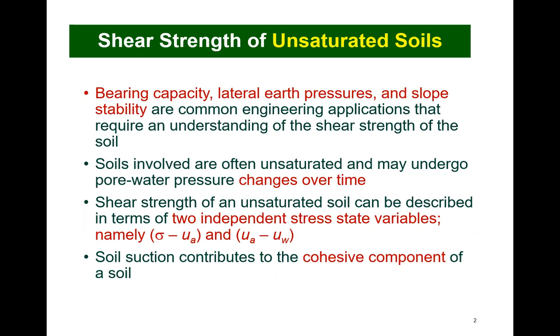The ground surface is also subjected to varying weather conditions, and as a consequence, the near ground surface pore-water pressures may change over time. The negative pore-water pressures add a type of cohesion to the strength of the soil. The shear strength of an unsaturated soil can be written in a mathematical form and then used to extend formulations for saturated soil mechanics such that it embraces unsaturated soils as well.